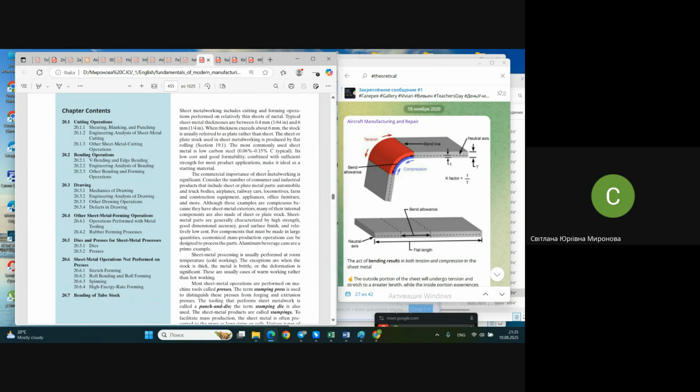Once again, if it comes to thousands of parts, of course, better to produce a metal punch and metal die block, no problem, when you need to produce some thousands of parts of the same shape and the same size. But when it comes to tens or maximum hundreds, it's not feasible.